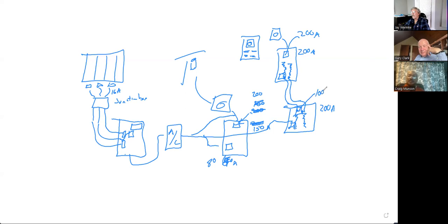I could put a 100 amp breaker here, and you could think, okay, I've limited it, but I haven't really, because if I'm back feeding the full amount through that breaker, I've exceeded it on this panel. Yeah, right. But this is usually used if you wanted to add a distribution network. Let's say you add on an addition, or you want to run it out to a garage or a barn or something like that, and it's all tied together. This is a lug panel or a main lug panel.